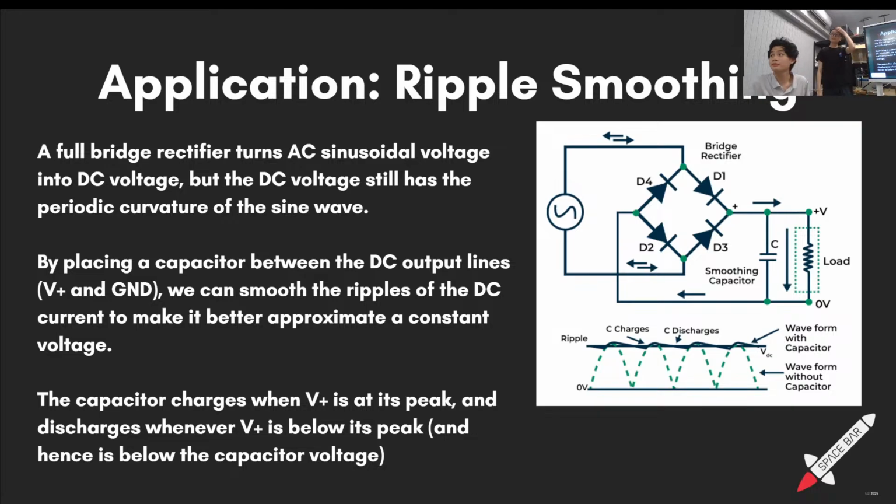After the first charge, will it ever fully discharge? Yes, because your load is still there. So it will discharge through the load when you turn it off. Once you turn off the voltage source, which is the AC source, there's still the load connected across your capacitor, so your capacitor will discharge through the load. It's no longer being charged at all. The capacitor will discharge through whatever consumes resistance. The load can be anything with resistance. Anything that sucks up the charge.